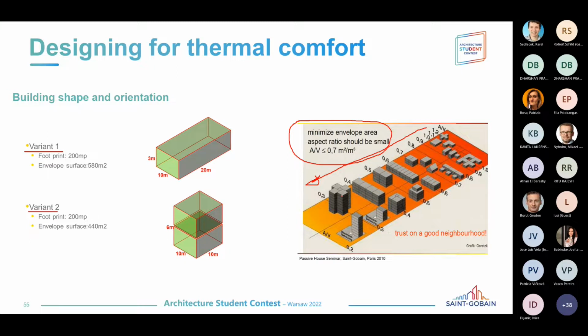bear in mind that the energy requirements refer to the heated envelope. So if you have, as we were speaking about balconies, balconies which are outside the heated envelope and which are also thermally decoupled or have thermal bridge breakers, then that part is not taken into account in the calculations.